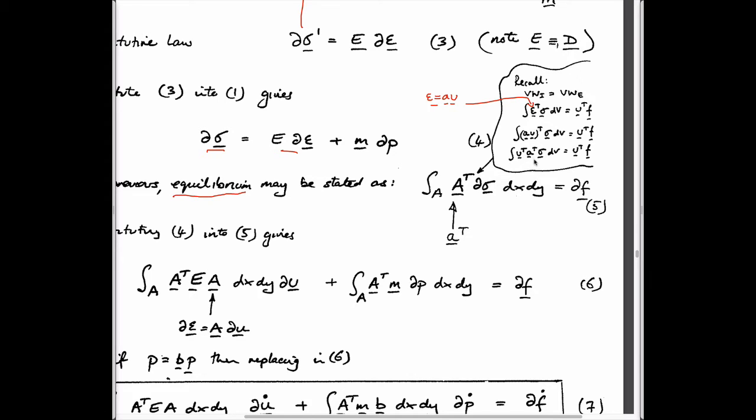I guess we also added, what else? Yeah, this is this, and this is this. And so what we then did, we actually put in the constitutive law here, right? Sigma equals D epsilon, but let's not do that. Let's realize that this here can be cancelled out with this here. And now the relationship we have links forces and these displacements. In other words, it's just this residual equation here. So it's just the same equation we had before. And actually this is kind of an equilibrium equation.